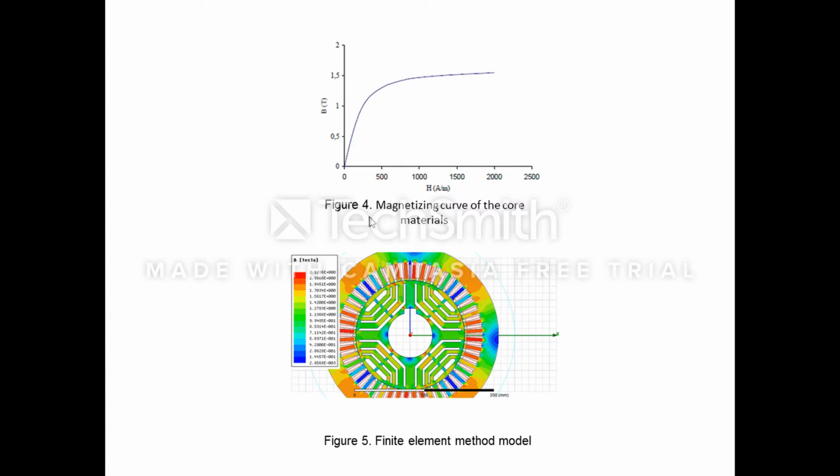Since the core material properties of MCSRM are the same as the core material properties of conventional SRM, the model of MCSRM has non-linear characteristic as well. The element defined by 8 nodes for the 2D model has been used in the finite element model of MCSRM. The element type has 3 degrees of freedom per node: magnetic vector potential, current, electromotive force.